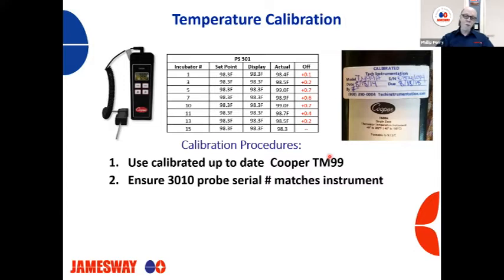And so when we got to looking, we were able to determine that all of these were anywhere from 2 to 3 to 4 tenths variation just in probes. So this is a very important aspect of your temperature calibration. If your calibration is wrong or your calibrator is wrong, it can take you 21 days to recover, because you have to go through and have that first hatch. And if you're using turkeys or ducks, it's even longer until you realize, oh, that could be my problem, I'm out of calibration.